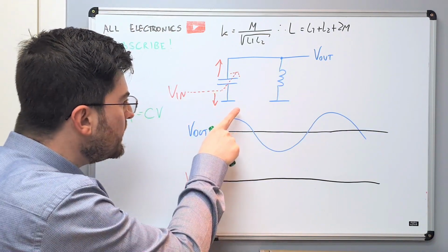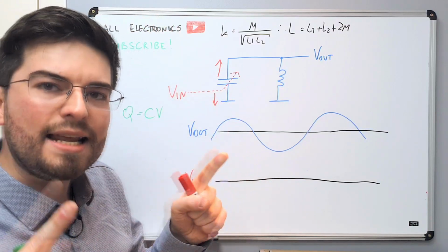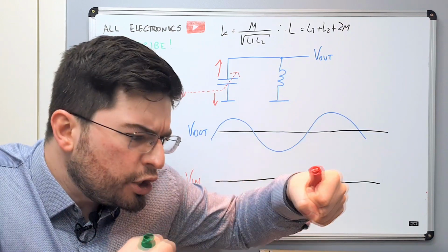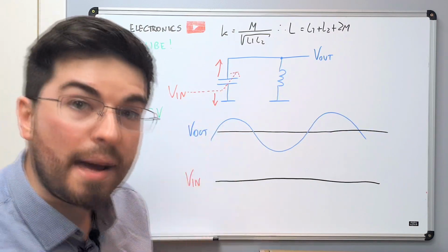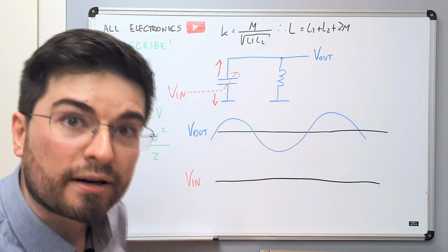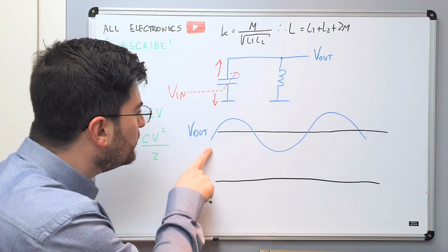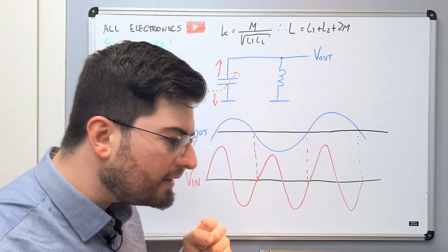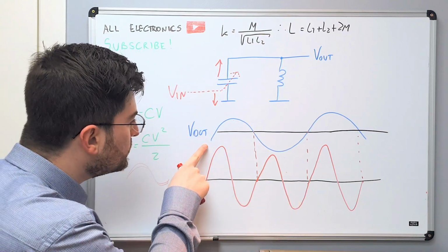Voltage is trying to increase, and we are actually increasing the voltage by pulling the plates of the capacitor. And in this way, we are adding energy. The mechanical force we are using to pull the plates is adding energy to the circuit. Remember, energy is proportional to voltage squared. So if we generate an increasing voltage synchronized with the oscillation, we are adding energy to the circuit. We injected energy into the system, pulling the plates of the capacitor when the voltage was going up.